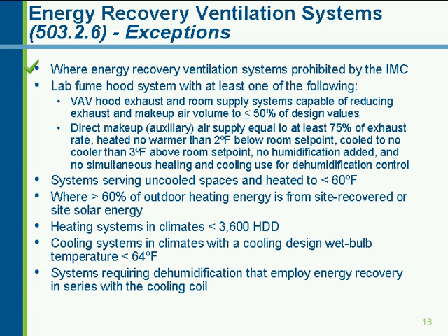If you've got direct makeup air to the exhaust hood system that's at least 75% of the exhaust rate and minimally conditioned, the requirements for that are heated no warmer than 2 degrees below room set point and cooled to no cooler than 3 degrees above room set point. You also cannot humidify that air, and you can't do any simultaneous heating and cooling for dehumidification control. So if you meet those requirements for a lab fume hood system, you don't need to do energy recovery ventilation.